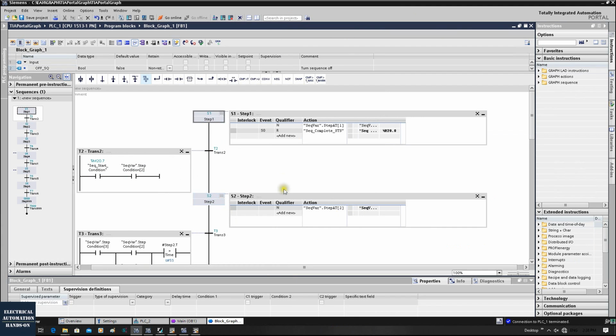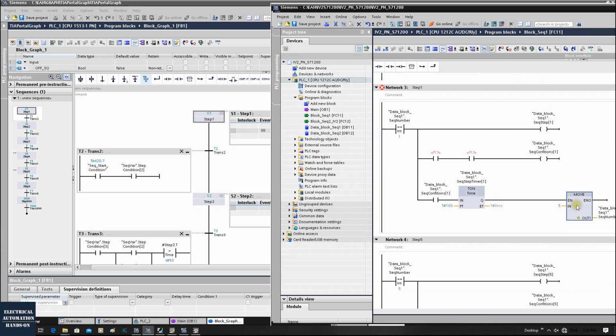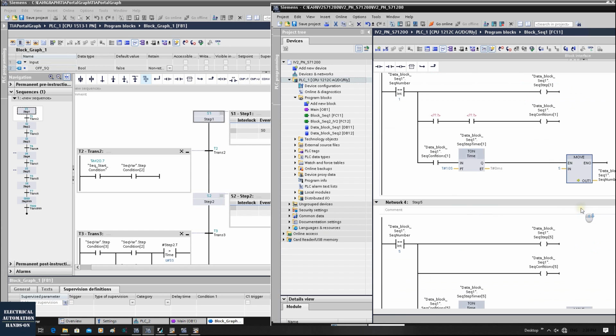And on the right side, the action area, back to the ladder logic, once we arrive at this step, we can use this signal as a command to control any other output, trigger a valve or servo drive control command, right? And this is the next step, which sequence number we will jump to. So for example, here I write 5, then we can jump to step 5.